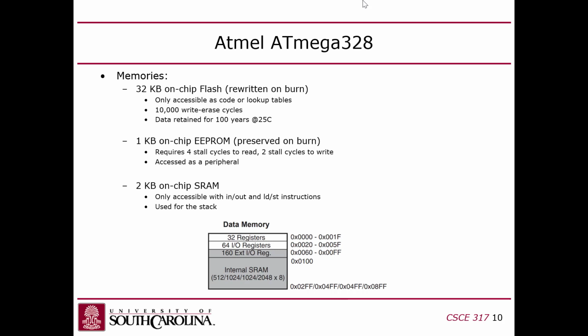You don't have that in an Intel processor or an ARM processor, right? There's an on-chip flash that's written whenever you program it. Whenever you program the chip, this internal flash gets burned. And the nice thing about it is it's non-volatile, meaning that unlike the FPGA boards we used in 611 and 313, when you disconnected the power and reconnected it, everything would be clear. The program would be clear. These chips will retain the program even after you disconnect the power.